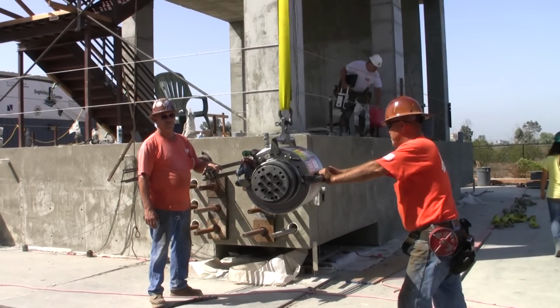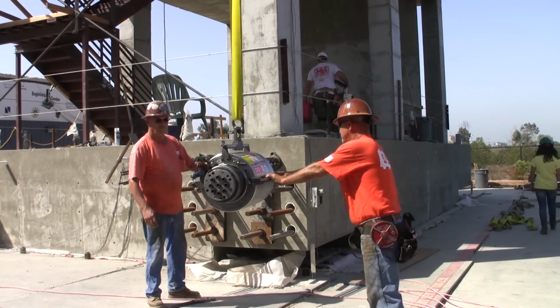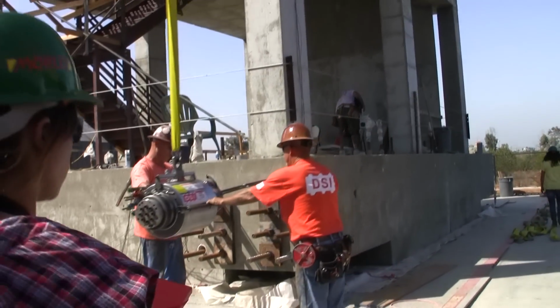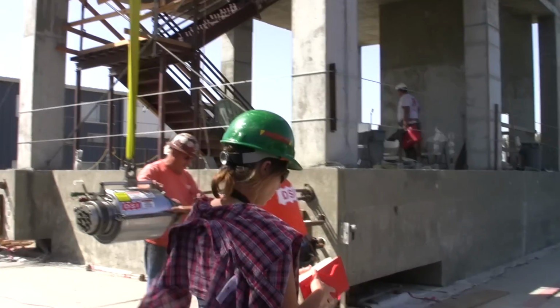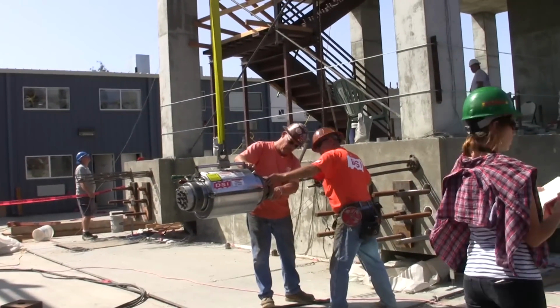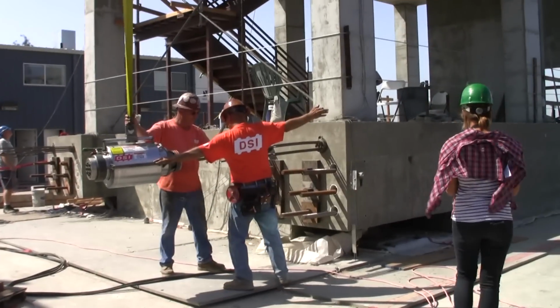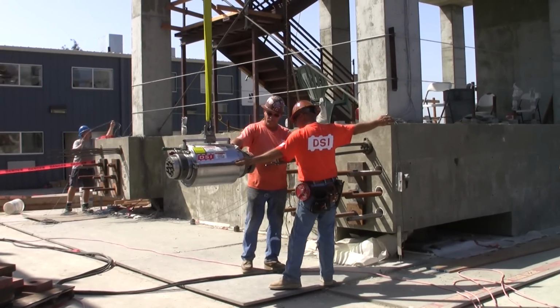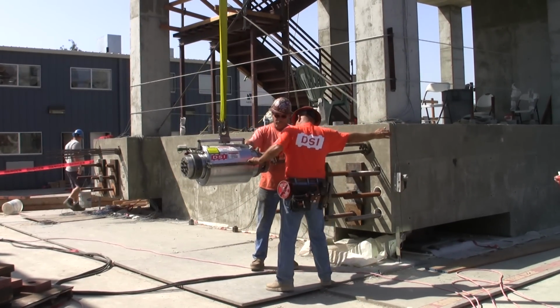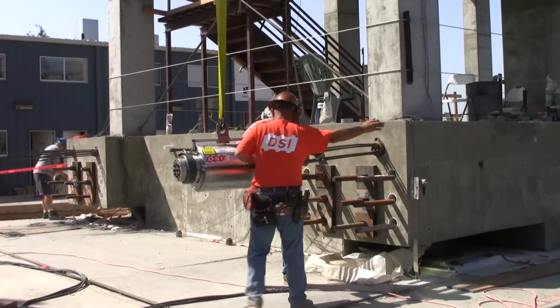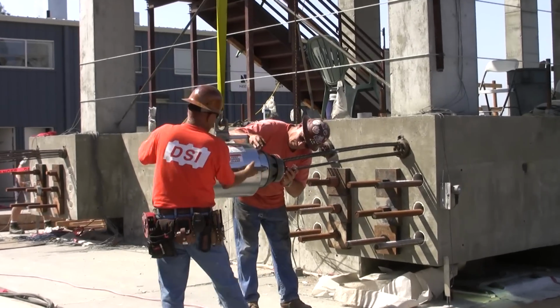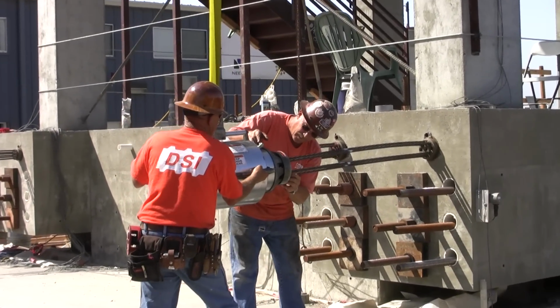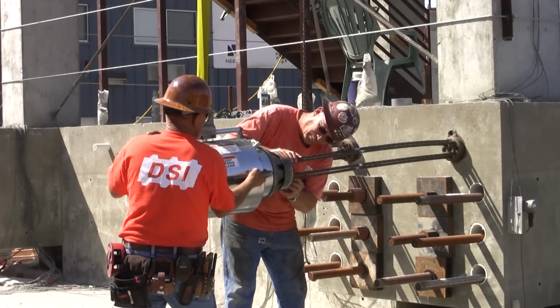The benefits of pre-stressing in general are that it allows for longer spans and thinner slabs, therefore requiring less concrete. In addition, thinner slabs result in less dead load, which improves the seismic performance of the member. In this project, both unbonded and bonded post-tensioning was used. Unbonded post-tensioning allows the individual cable inside the voids to move freely relative to the concrete. This method is used less because the concrete can de-stress naturally, therefore limiting its potential to the structure.